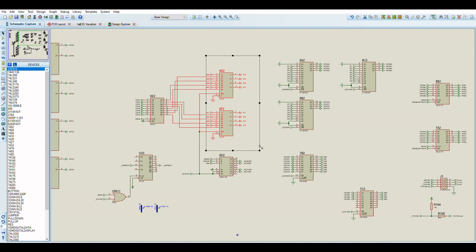Say, for example, we are rendering pixels and looking up pixel values in the palette RAMs. So we are not writing data, so we do not select the address from the external memory bus. We use the pixel value itself, which is 3-bit planes plus 5 bits for the palette index. We use that to directly calculate the memory address into the 3 palette RAMs here.